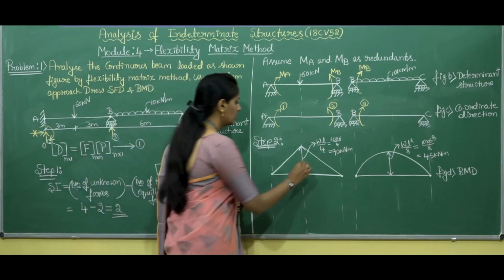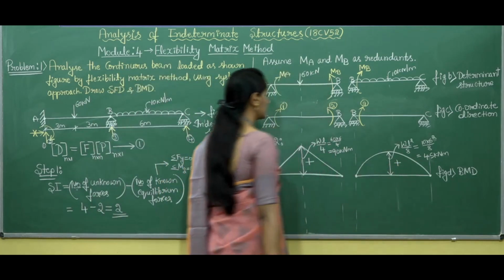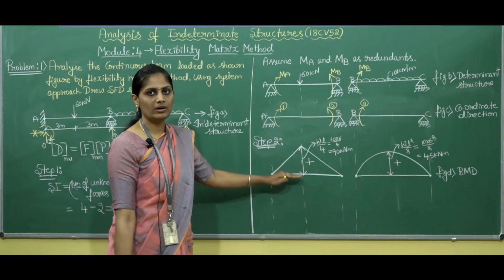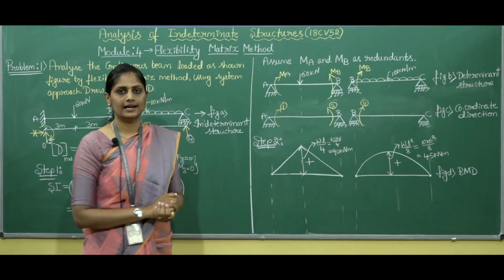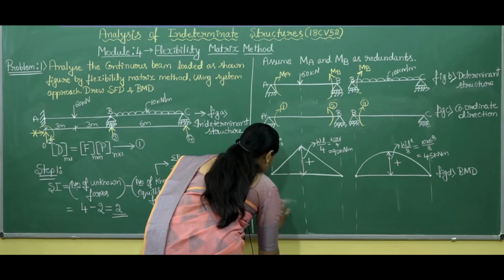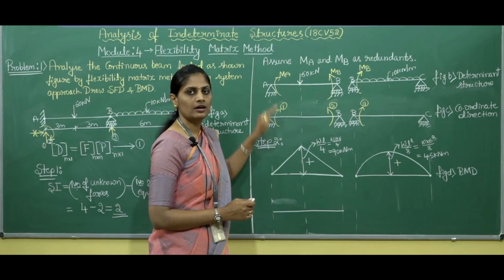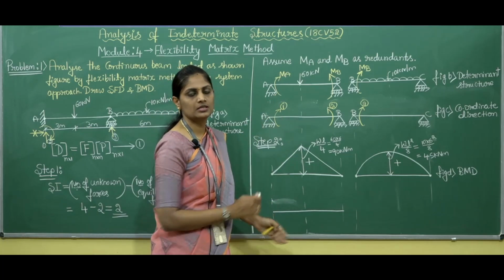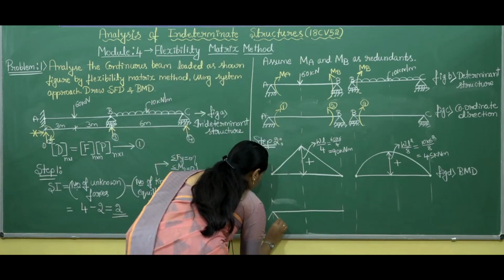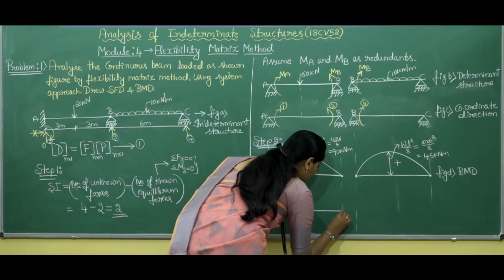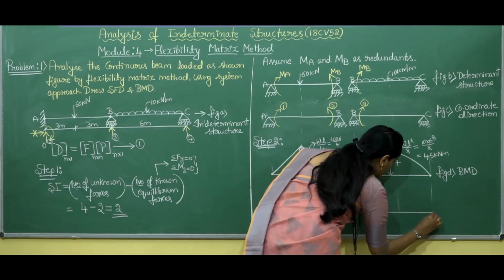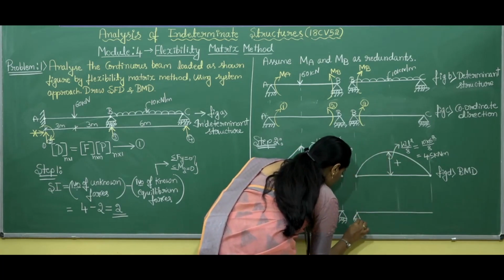So, now let us sketch the conjugate beam. That means we need to load these bending moment values on EI diagram. That gives us the conjugate beam. You know simple supports remain as simple supports in the conjugate beam. Therefore, at A, at B and at C we have simple supports. Therefore, in the conjugate beam also the supports remain as they are.